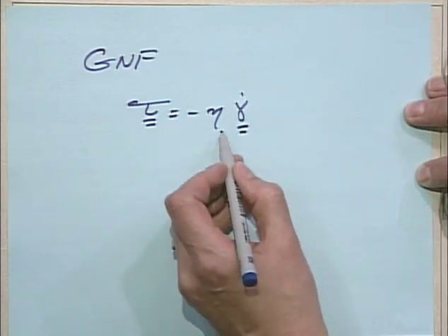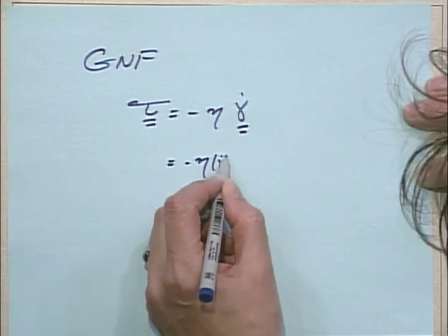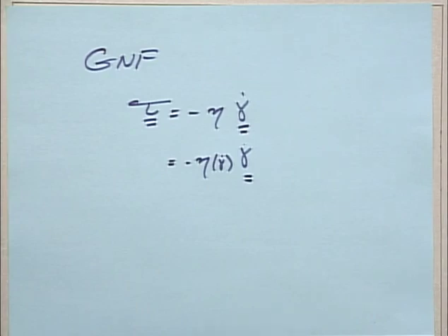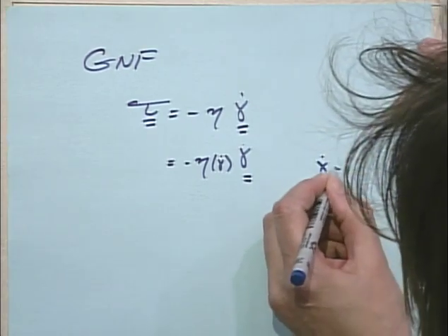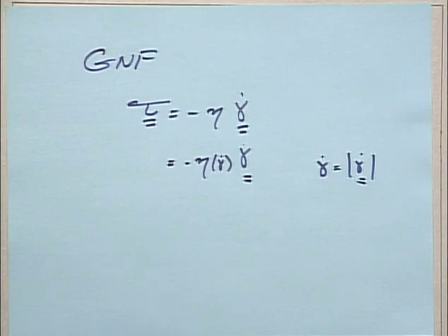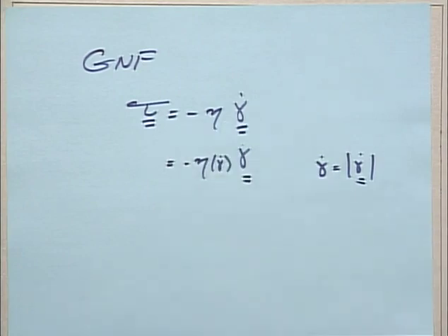There are a variety of these viscosity functions, so sometimes we write this as eta of gamma dot, where gamma dot is not the shear rate. Gamma dot is the magnitude of the rate of deformation tensor. There are some things like that in rheology with nomenclature that are a little bit off-putting, perhaps. So for instance, in this generalized Newtonian fluid, this viscosity function appears.